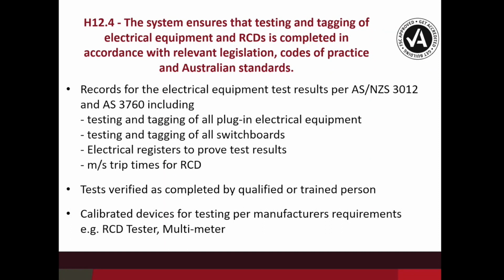We follow that very strictly, and it will talk about test and tag and plug-in equipment, switchboards, the registers that we require, or the information that we require to prove that the tests have been completed, and the test results. One of the things that quite often comes up is recording the milliseconds, milliamps and things like that for the test results when we're testing RCDs.